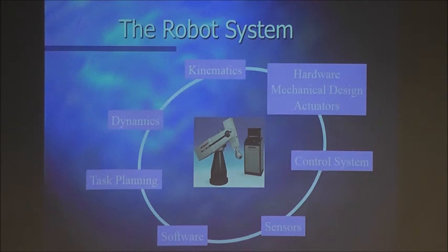If you look at an industrial robot like the ABB, it has 6 degrees of freedom, from base to shoulder to elbow and to wrist, which has 3 different motions: pitch, yaw, and roll. So you have 6 degrees of freedom, and that is enough to work in three-dimensional space.